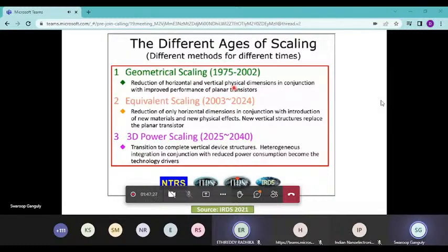The first era, most of you, I presume, are young people, so this is before your time, essentially, when scaling was very simple. Moore's law, I mean, implementation of Moore's law was relatively simple. You had to miniaturize the CMOS device. Well, it at least looks simple in hindsight. It wasn't perhaps so simple then. You had to miniaturize the device, so you had to manage the electric fields by doping and other device engineering.